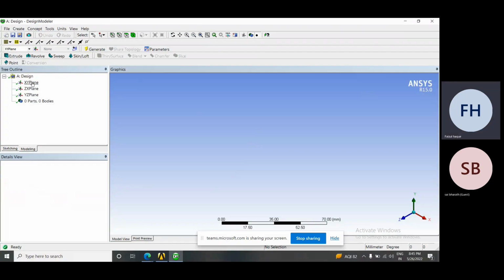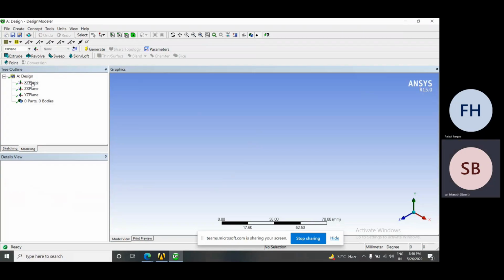Have you studied AutoCAD in 3D also, or only 2D AutoCAD? Yes, sir, 3D also. Okay, so we will explain this easily. In 3D, when we move from top to isometric view, we get four modes: southeast, southwest, northeast, and northwest.